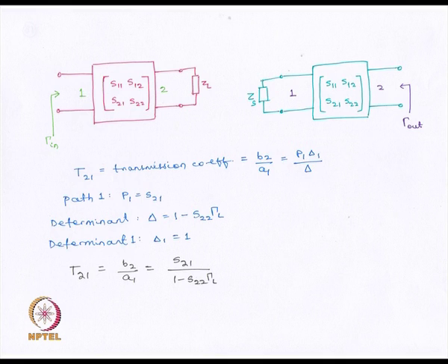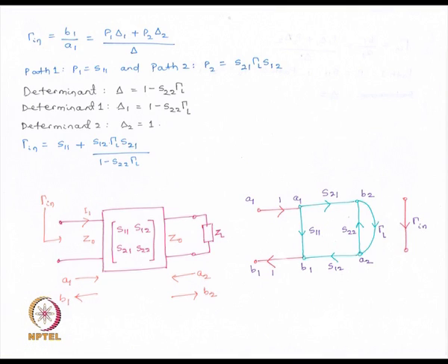Delta remains the same, and since this path P1, see this starting from A1 to B2, it actually touches this loop, and when I say non-touching, it means non-touching at all, including nodes or paths. Nothing in this loop, including the nodes and paths, should touch anything in this main path, including the nodes or any subpaths.